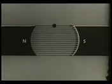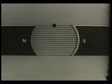As the conductor keeps turning, the number of lines cut increases so that at a quarter turn or 90 degrees, the maximum number is being cut and maximum EMF is generated. Again, at 180 degrees, no lines are cut, no EMF. We reach a maximum again at 270 degrees, and finally, again at 360 degrees, no lines are cut. The conductor has rotated 360 mechanical degrees, which correspond in this instance to 360 electrical degrees.